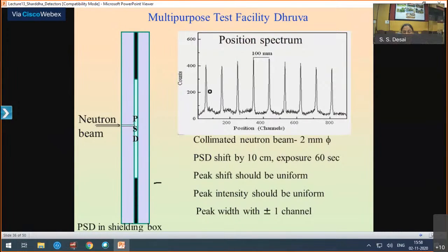Any non-linearity should not be seen in this output. This is a measure not only of the detector hardware but also of the symmetry of the external pulse processing electronics. Any non-uniformity does not necessarily mean that a wire is sagging at some place; it is also a measure of how well your electronics is tuned for equal gain in both the branches.